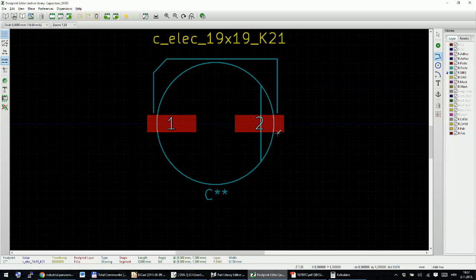I will go over here, press enter, go all the way to 8.5 and 9.5, press enter and extend all the way to 9.5 here and go back 4, up 4. Oops. I need to delete this one, so I need to press enter here again. 1, 2, 3, 4, 1, 2, 3, 4 here, and I will go up. I'll double click it, and this is our capacitor.